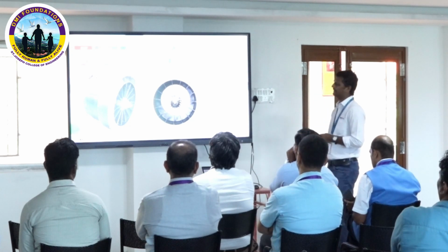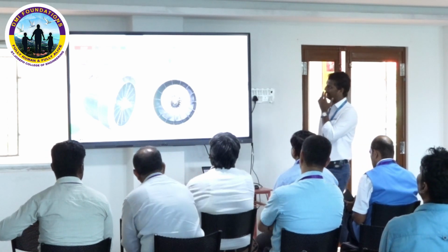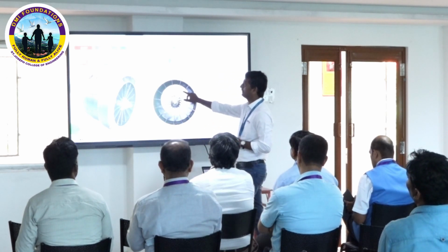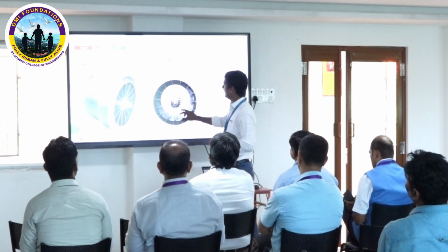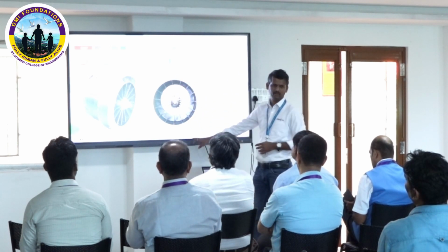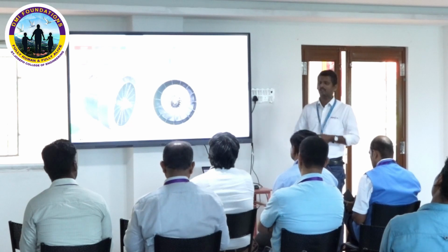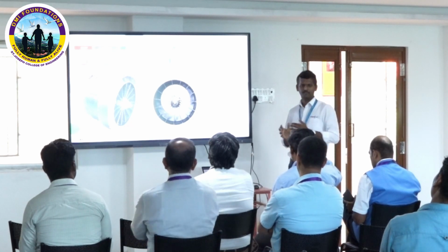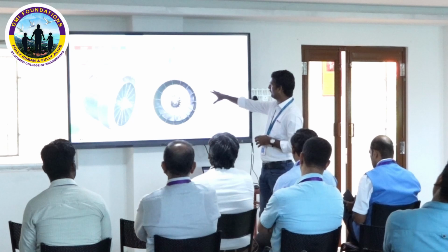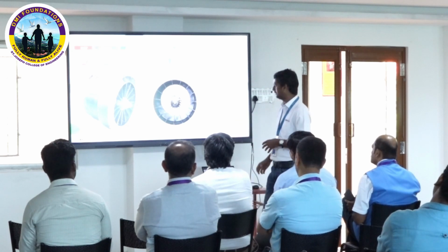And this anti-icing article, here it is not one single component, 3 different components are there. One is these blades. These blades are made up of Ti-64. And the center part is made up of Inconel 718, and the outer ring is a conventionally made one. So this is being used in the front of the aircraft, so that icing kind of issues will be reduced. You can see the diameter of the overall thing is 1 meter, which we can't print. That's why we go for printing the things separately and getting them assembled.